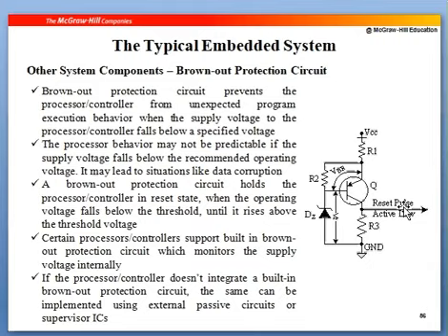Now the transistor will be in the on state when VCC is greater than the sum of VBE and VZ. So if VCC is greater than VBE plus VZ, this transistor will be in the on position. Suppose the sum of VBE plus VZ is greater than VCC, then the transistor will be in the off state.